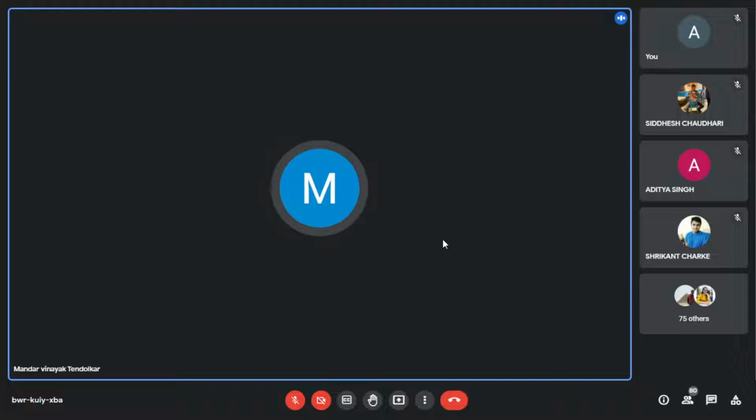On the top, we have this large head called the power head. There's also a coil of very thin tubing known as the capillary tube, and there is a large bulb at the end of it known as the sensing bulb. These are all made from stainless steel. The coil is stretched out so that the bulb sits at the exit of the evaporator to sense the superheat. We have previously covered in great detail how thermal expansion valves and electronic expansion valves work, as well as the different types of expansion valves used on chillers.